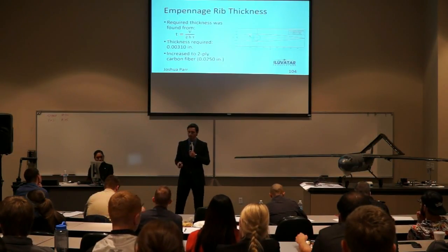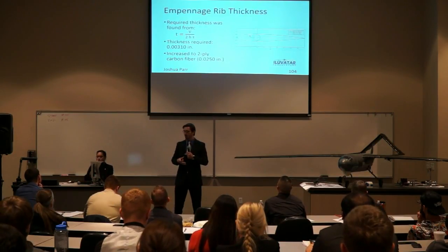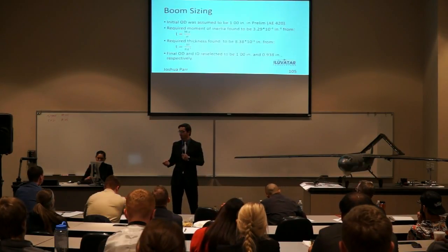Then you have thickness required was 0.003 inches. And this is increased, once again, to 2 layers of carbon fiber, because that was our minimum that we're going to do for any component. That was 0.025 inches, so we were plenty thick on that.